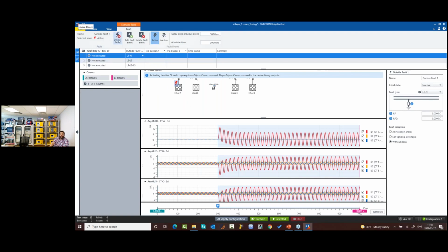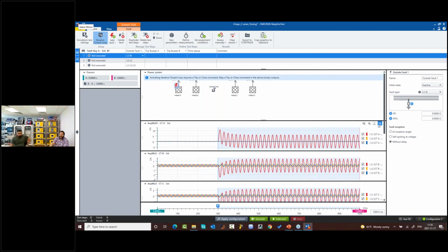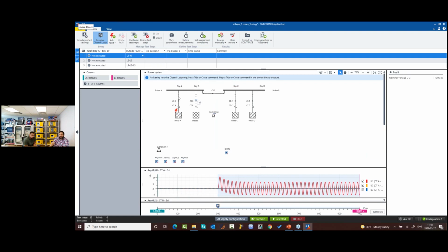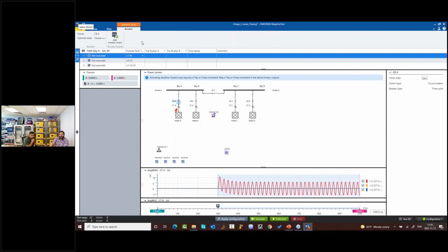And luckily here also we have something like breaker fail. If you select the circuit breaker, you can find it automatically assigns the breaker fail for this breaker, for example, or maybe this is the external. I will select this circuit breaker, and if you select the circuit breaker, you have here an icon, and with this icon you can add a breaker event, when it will open, when it's closed, and you can also make it a breaker fail, to continue closed without opening, even on a trip.